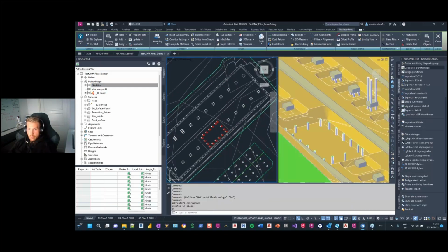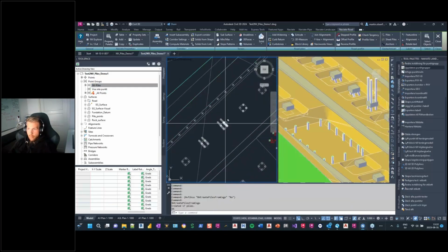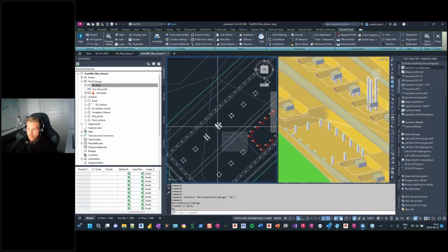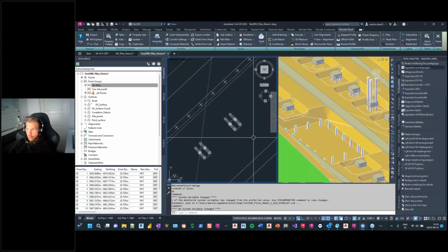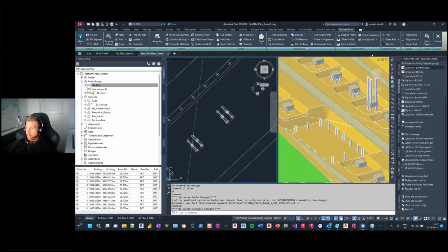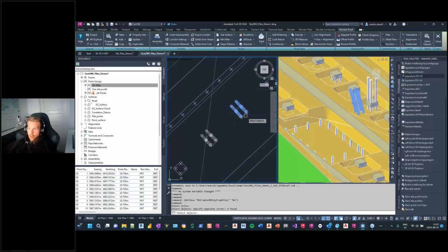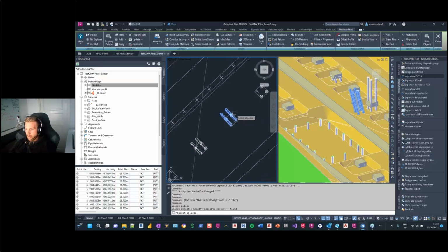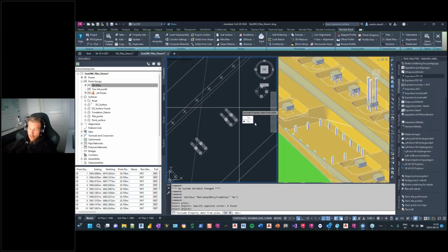So let's move on here. If I want to export those points as 3D polylines to a contractor surveyor for stakeout, we got the last function on piles, that is create 3D polylines from piles. So if I run this function, I can just mark the points or the piles I want to export as 3D polylines and hit enter. I can also choose if I want to include property data on those 3D polylines. If I don't want it, I just hit no.